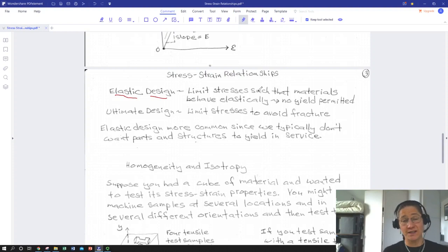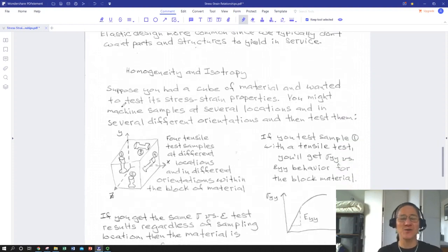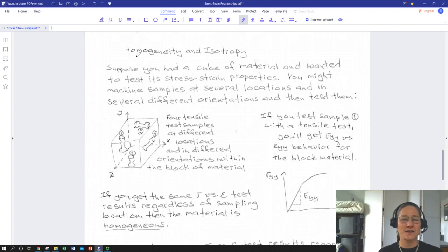Composites unfortunately suffer from that. So you might be doing an ultimate design if you're designing a composite material simply because it might be fracture prone. Okay, not that composites are the only materials that are fracture prone. There are some metals, but composites definitely have that as a challenge. They also have a great strength to weight ratio, so it is all a trade-off.